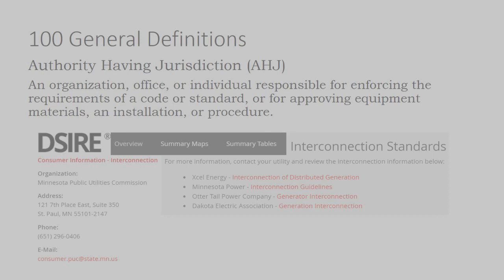And so they're settling on a knife switch disconnect, and it's not part of National Electric Code. So whenever you're doing any kind of solar design, if you design to National Electric Code, you can still make design errors and fail your inspection, because there may be additional jurisdictional requirements that you have to abide by.